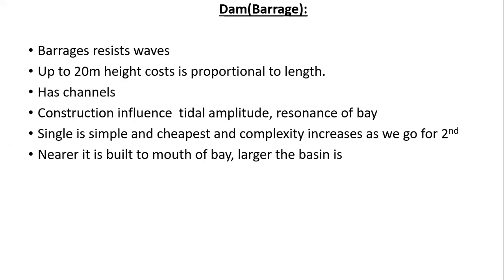Now coming to the dam or barrage, we will describe each one briefly. First one, the dam or barrage. These terms are synonyms, both are equal only. Barrage has been suggested as more accurate than dam because for tidal power plants it has to withstand heads that are a fraction of the structure's height, and the stability problems are far more modest. So the problems encountered in the dam are overcome in the barrage.